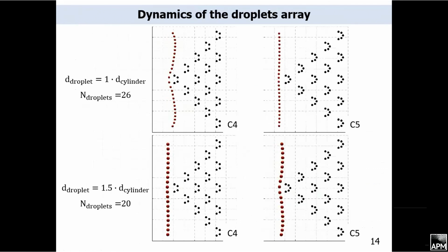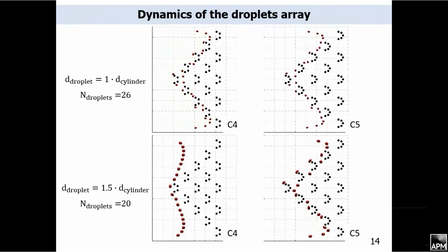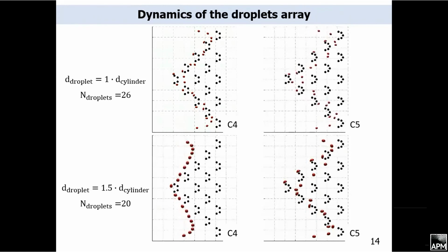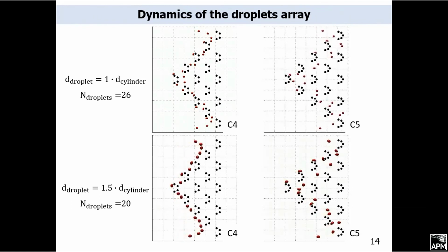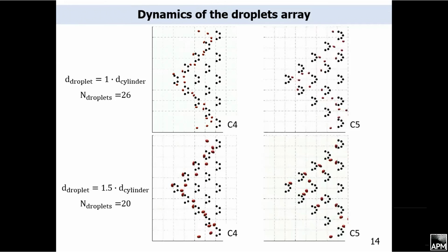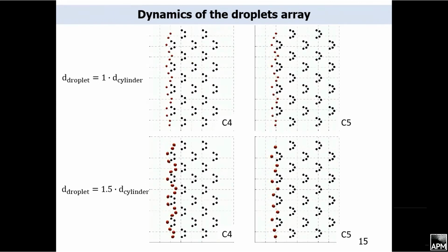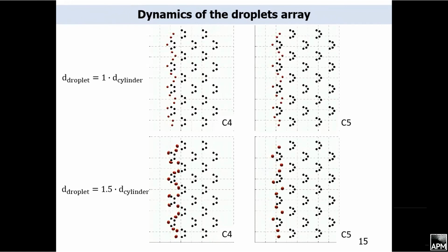We consider dynamics of several droplets in microchannels with trap arrays with different arrangement. These videos demonstrate the motion of droplets in a channel with a triangular array of traps. Droplets pass by the triangle array of C5 traps due to the flow redistribution and hydrodynamic resistance increasing. On these videos, you can see the motion of deformable particles in a channel with a chess array of traps. This traps arrangement is more effective than triangular. It is more promising for further study.